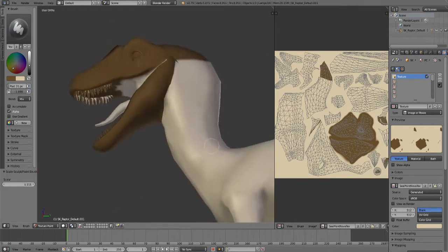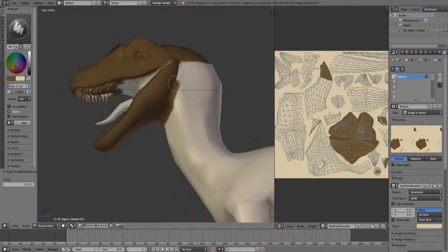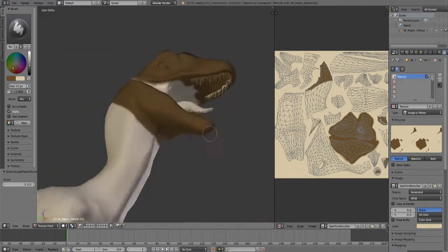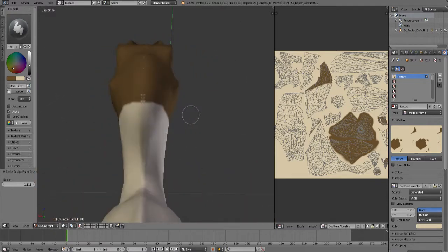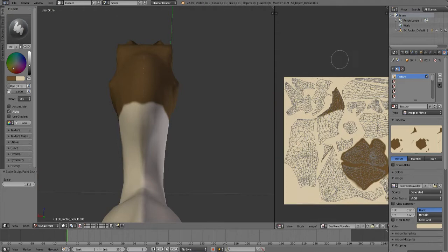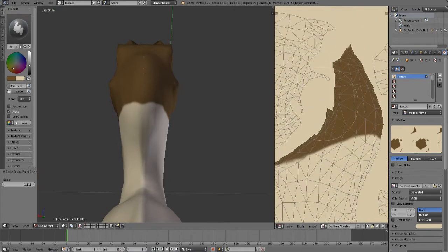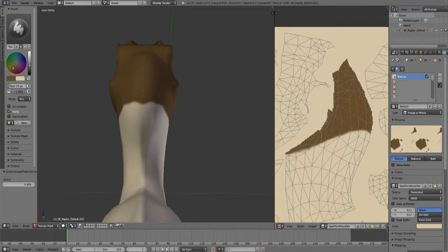Always overlap the UV map edges. Leaving the seams visible like that will ruin your composition. Little spots on the island seams will show up, and they are difficult to paint over in the viewport. The edges of the UV image editor look like they were drawn in MS Paint, which is why this happens. To fix this issue, simply paint along the island edge without painting within the other islands.